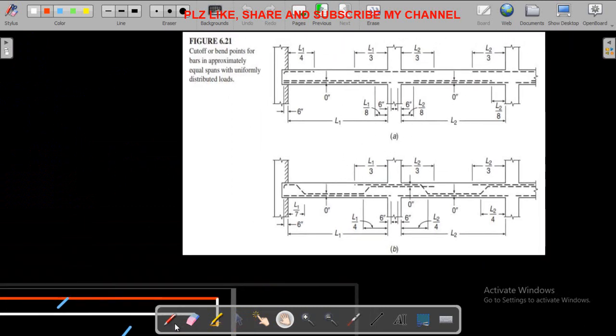So let's say if you are using the curtailment. Now for curtailment, you can see the bar in the top will be cut off at a distance of Ln/4, while this is just for the simply supported edge. And from this side it can be cut off at Ln/8.